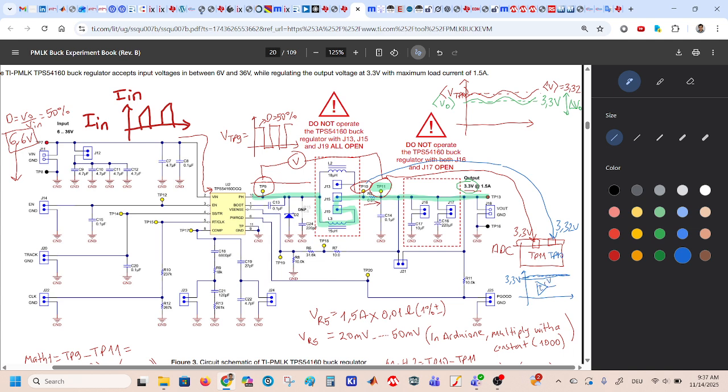What is the supply voltage, VCC, of Arduino? You should check in Arduino what is the maximum allowable voltage signal that I can feed here. If Arduino tells me that you can feed the channels with more than 3.3 volts, for example, with 5 volts, then the op-amp can work with these voltages.